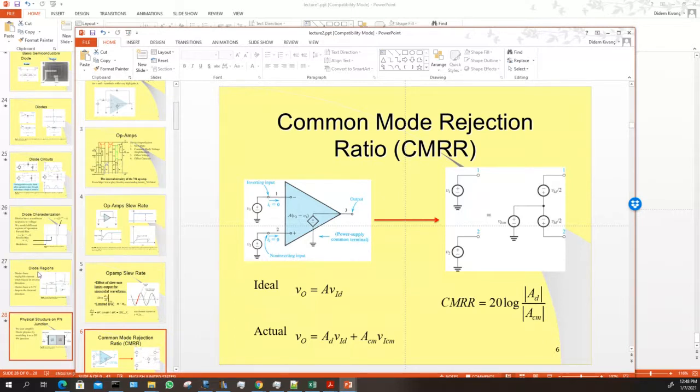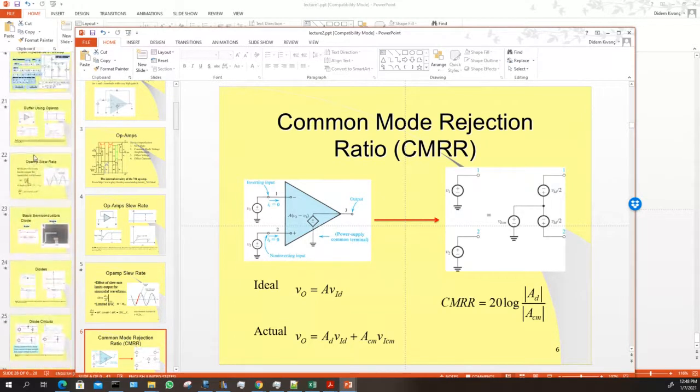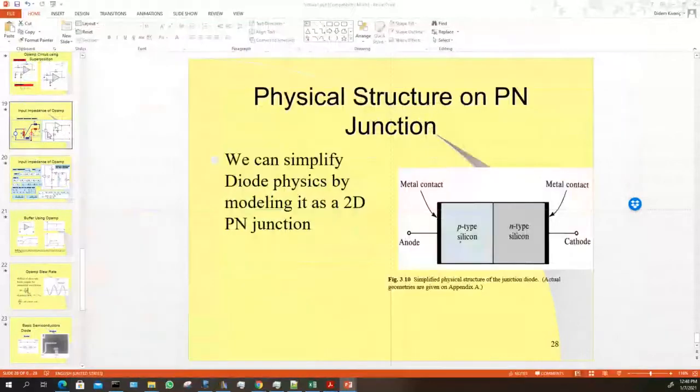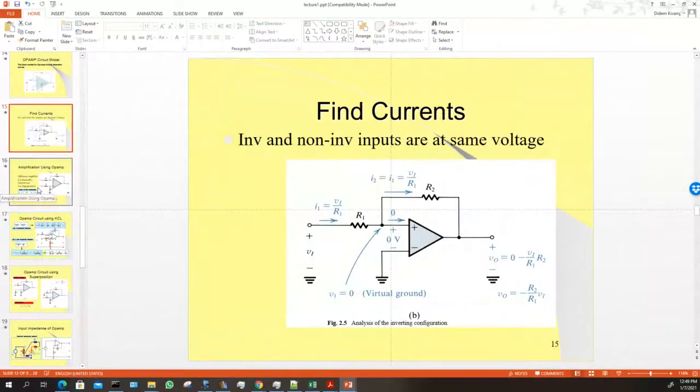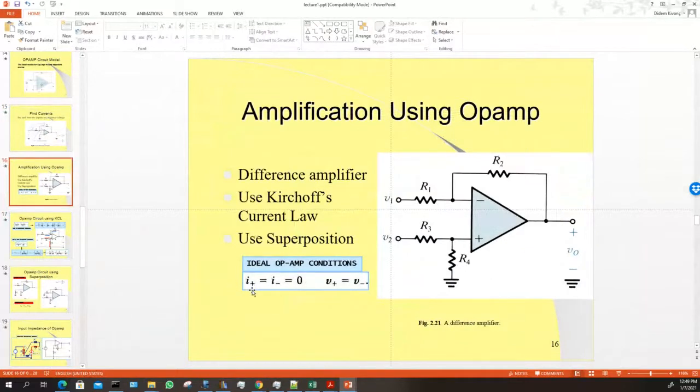So if you look at op amps at the very basic level, there's like 2 or 3 equations. Op amps are the most fun thing to analyze at this basic level because there's like 3 equations there. I plus is 0, I minus is 0, V out is equal to V input, and you just solve all these equations really quickly.